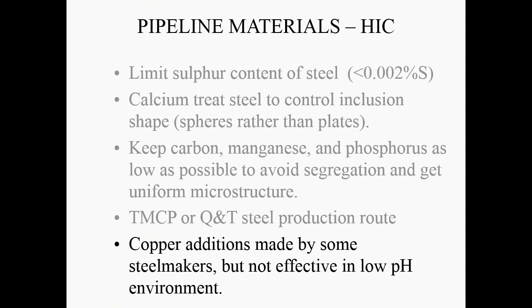Adding copper to the steel makes it more likely that you form the Fe2O3 with a little bit of copper in it. So if you look at the Angel of the North, it looks slightly coppery in its colour because we have these copper oxides present in the surface as well. And that weathering steel is great, but it's only good for atmospheric levels, because if the pH gets too low, that surface is damaged. So when you have pipeline systems containing products that have large quantities of acid gas or large amounts of CO2 in, then it's probably not effective.